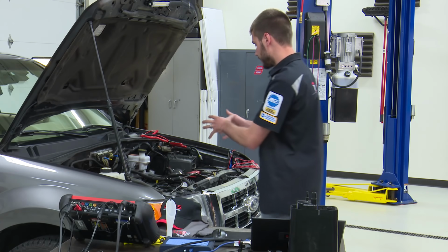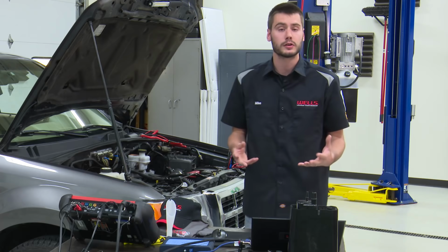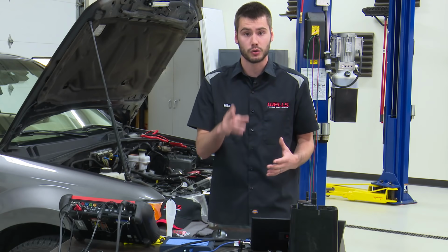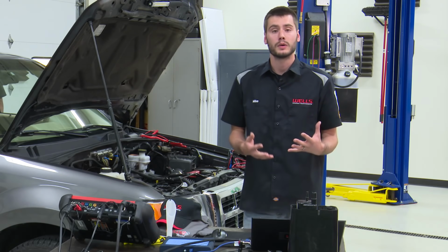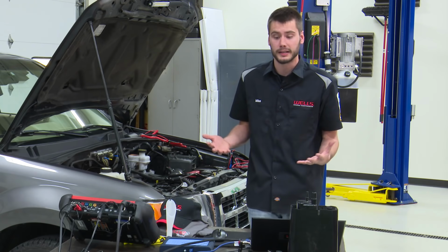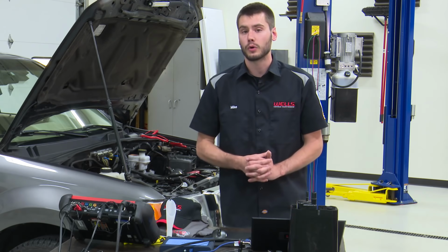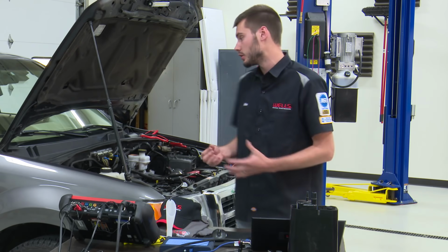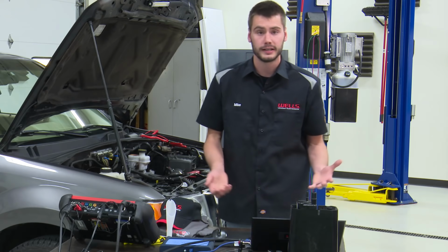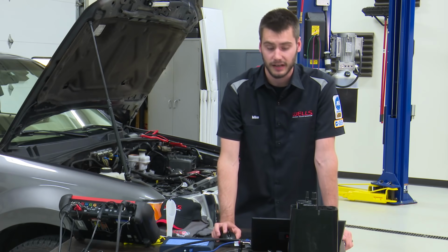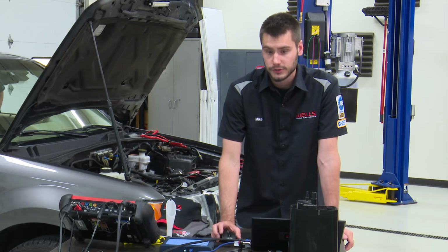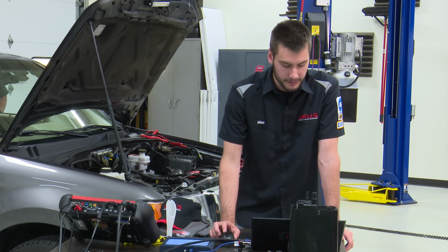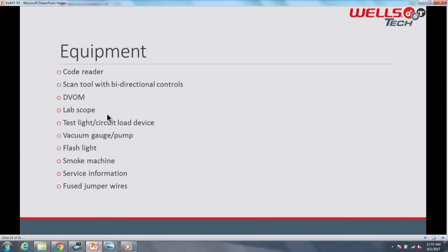When we have our vacuum pump, we have our vice grip, which would be our purge solenoid, that's our door, cutting off the vacuum. We have a pressure sensor already. What is the point of going through all of that extra work, hooking that all up, when you have it available on the vehicle already for you to use as long as the engine is idling and under vacuum? So he hasn't replied yet, but my only thought would be maybe if you don't trust your fuel tank pressure sensor or something at that point.